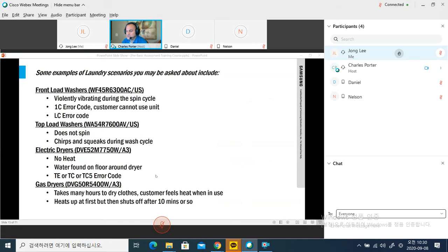240, of course, is an approximation. It's not always going to be that. It might be 235, might even be 220. But approximately 240 plus or minus 10% or so is what you're looking for. You really don't want anything less than, say, probably around 210. Once you get below that, then you're probably going to have some issues inside there. But yeah, 240 is what you're looking for at that outlet.